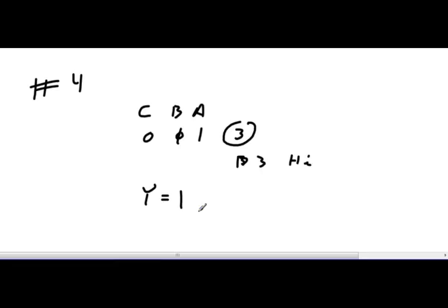C is the most significant guy. And I see I have 5 volts hooked up to A and B, and I see C is grounded. So that means I have 0, 1, 1, which is a 3, which means I'm selecting D3. I look at D3, and it has 5 volts hooked up to it. So that D3 has to go to Y.